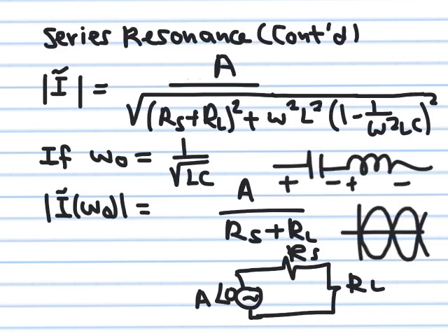And as a result, the net voltage that you can measure between these two terminals, which is the sum of the two voltages, will be 0. So suddenly, this LC series combination behaves like a short circuit. Okay, and this results in the current in the circuit suddenly peaking. At any other frequency other than the resonance, the impedance is significant.